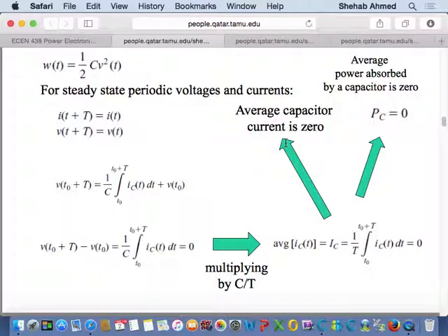It also confirms that if you have a circuit with an ideal capacitor, there's no power consumption in the capacitor. Capacitors will store the energy. Yes, they will, and that's why we will use them. But there's no power consumption in an ideal capacitor. Real capacitors are not ideal. Real capacitors are modeled as an ideal capacitor in series with a resistor. That's a simple model. So they will consume power, obviously, because these capacitors are made of conducting materials, right?